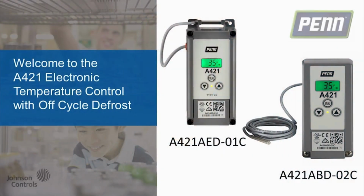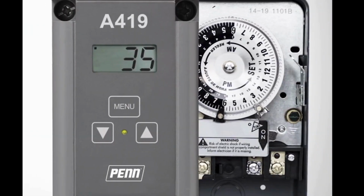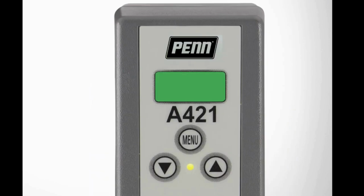This video will help you to identify and program the A421 electronic refrigeration controls with off-cycle defrost. This control combines the functionality of an electronic temperature control with an off-cycle defrost timer. The A421 with off-cycle defrost can only be used in medium temperature refrigeration systems. At preset intervals, the control will shut off the compressor for a selected length of time.